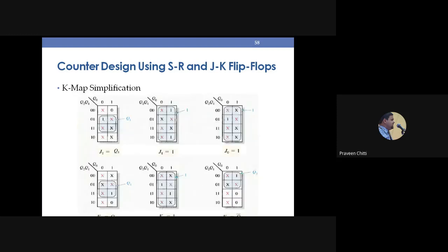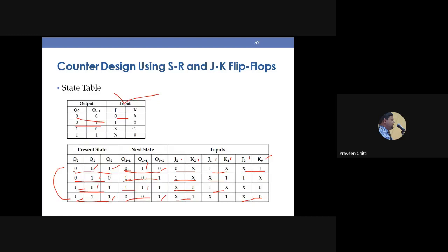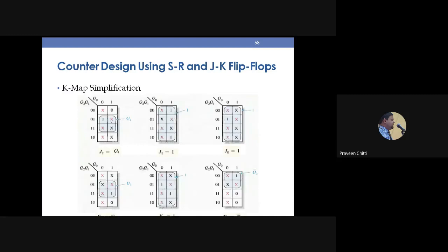You can see here, these 4 I have entered 01XX, that is 001 is 1, then 010 is X, like that you have to enter, and the remaining you have to enter X, and then you can form a group like this. You will get one quad, right?